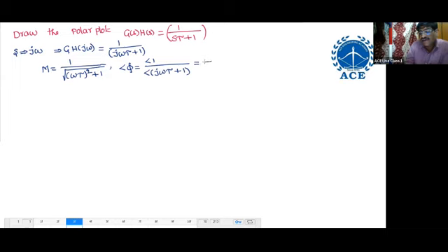Angle 1 is 0. Angle of J omega tau plus 1 is tan inverse of imaginary part by real part, that is tan inverse omega tau by 1. So the phase is minus tan inverse of omega tau. Okay. Now, come on, draw the plot.